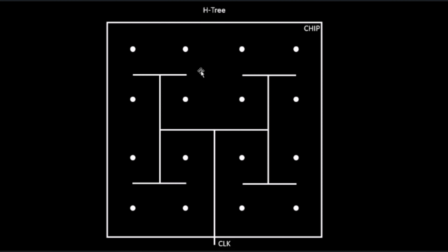That makes it very easy to connect them. So that's the purpose. So you can understand how building this small H tree has helped us understand the concepts of building an H tree for advanced designs, or for millions of flops. For millions of flops, you need to divide into small pieces or small squares, and each square or each area should have the same number of flop endpoints.